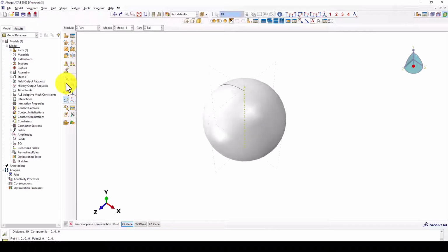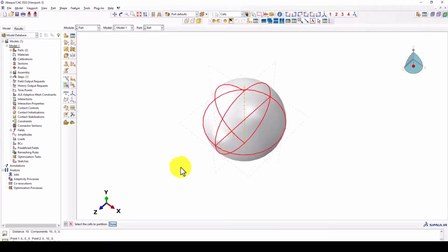The event occurs extremely quickly, stress waves become extremely important, and the response can become highly localized. Depending on the velocity and material involved, we may observe severe plastic deformation, fragmentation, penetration, material failure, erosion, and shockwave effects.